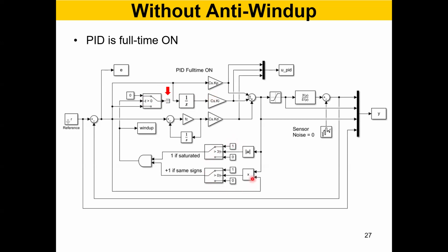The rest I explained to you the other day, how we get the saturation detected, all right? When the control signal is saturated and at the same time, the control signal and the error have the same sign, right? We combine these two together. If that condition is satisfied, we turn off the integral controller temporarily. Okay, right. So please download those files and put them in one folder on your machine, run the MATLAB code, then you will see the results. After that, you can change it a little bit here and there, right, to explore.